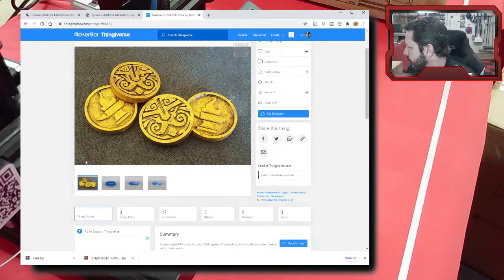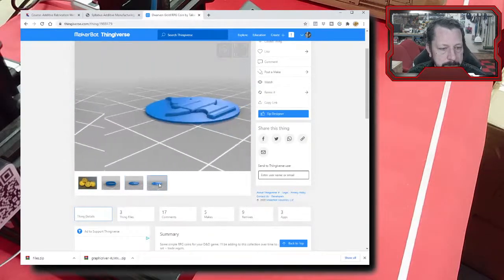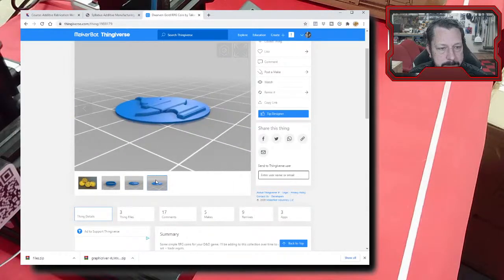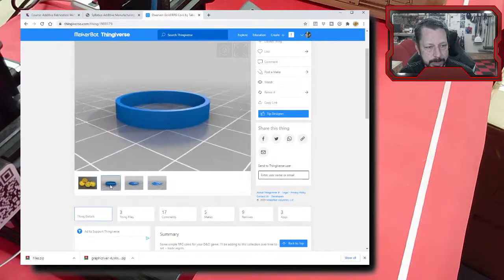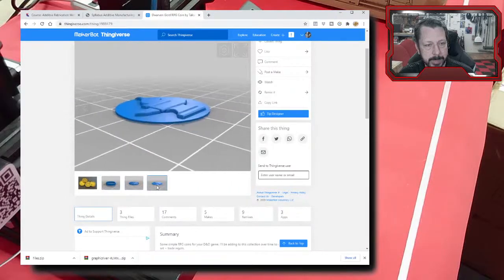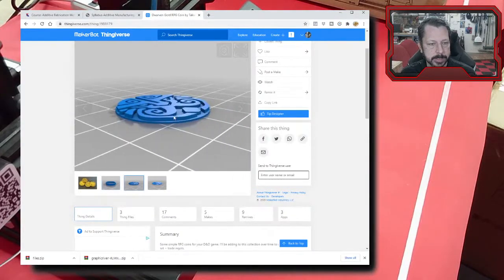They even have gold filament, sort of gold filament in here. Not yellow, though. Oh, this one's in multiple pieces. Let's just print the top piece. Apparently you assemble this. Oh, because it's got a back on it. So this is one of the things that you'll start to see about 3D printing: the printer can't print in midair. So if you have a part that needs to be in midair, then you have to figure out a workaround. In this case, they built a ring and a top and a bottom, print them all facing up, and then glue it together later. Let's just print just this piece.